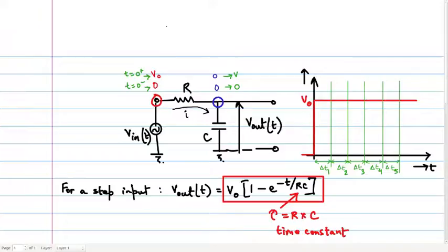The capacitor, on the other hand, will not let this current through, as has been discussed earlier, but will take the charges pumped in by the current and deposit them on its own plates. The capacitor voltage now rises, and since that's also the output voltage, we can plot it on the graph as having risen to some value. Let's call it V1.